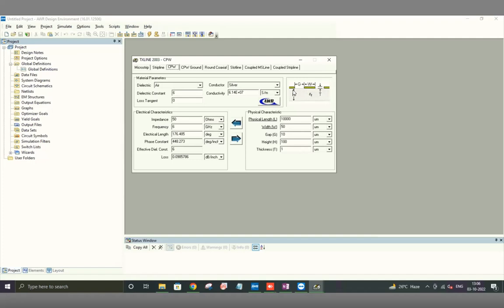And it has 2 ground planes on either side, but horizontally, laterally, as opposed to the strip line which was up and down. So remember, strip line was like this. Now this is the center, and this is ground and ground. And now you have something like this: center plane and ground, ground. And there is now a gap between the ground and the center plane on both sides, and it's usually symmetric. So this gap and this gap are always made the same.